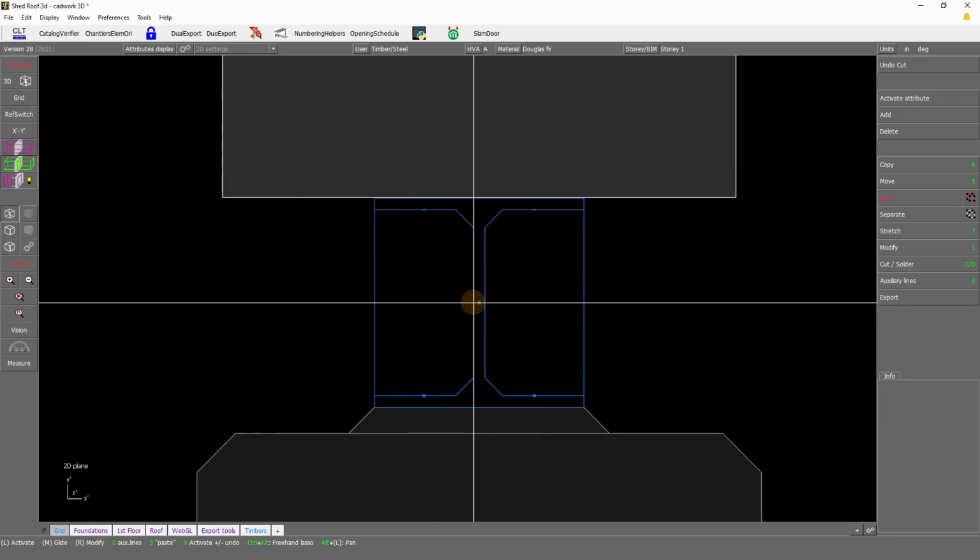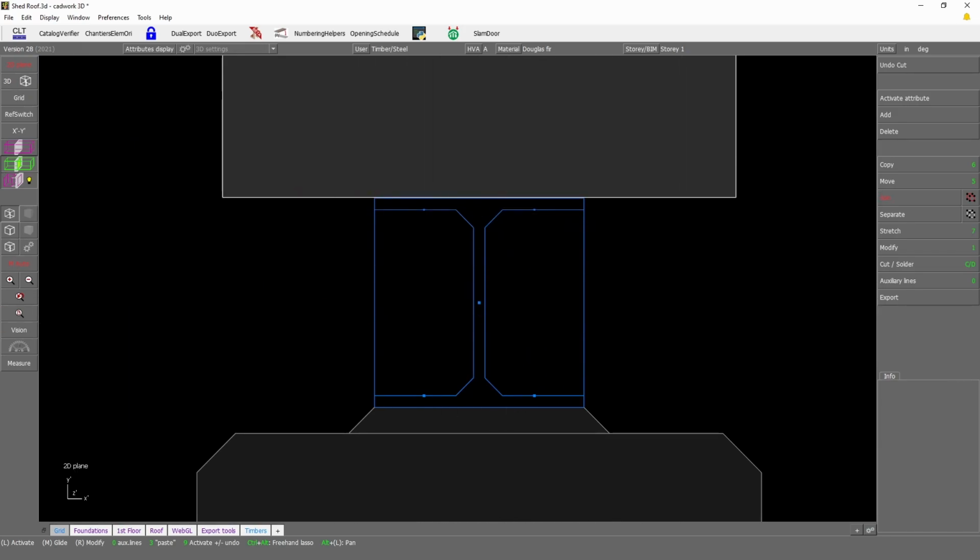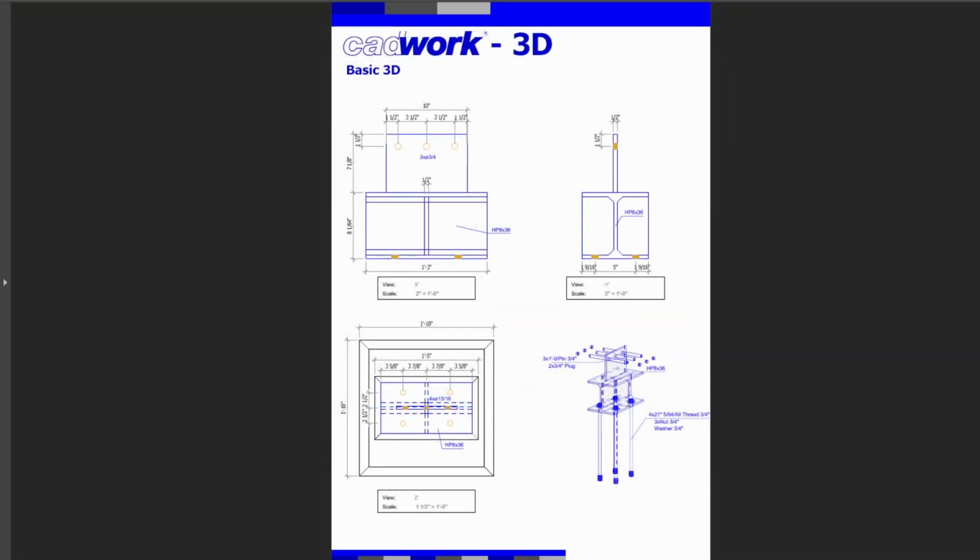Since we are in that view, we can actually add directly the knife plate that should be added here at the top. So this element is 7 1/8 high, 10 inches long, and half an inch thick. So it means it's mostly the same as this one.